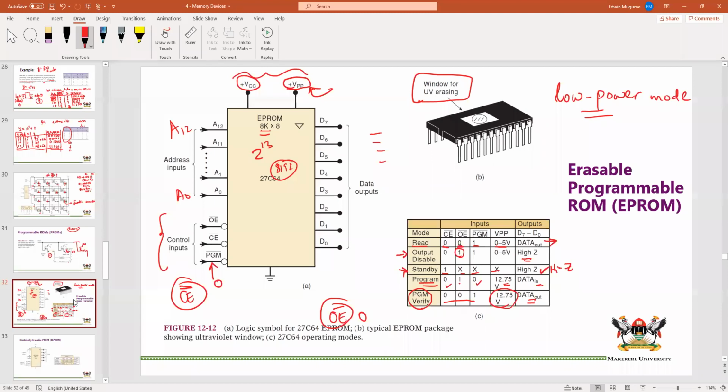I think it would be the same. A fusible link, a melting link, because usually a fusible link means that you have a fuse. So if you look in your plug at home, or the plug in your laptop, there's a fuse that connects two terminals. That's a fusible link. If there's a problem with power, if it is an overvoltage, it will blow so that it protects the rest of whatever is behind it. And so I've never really had the term melting link, but usually when we have a fusible link, we can melt it, and then we have an open circuit. So it sounds like it would be the same, Arvin.